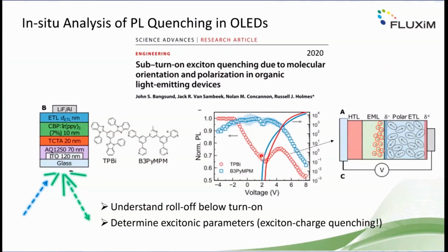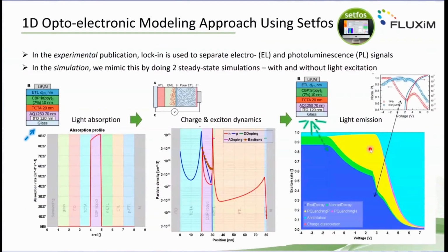For that measurement, of course, you need to excite the photoluminescence by optical excitation, but at the same time there's a voltage scan happening, as this graph shows, from reverse to positive bias. A voltage is scanned, and those carriers that are flowing or which are accumulated at interfaces do influence the photoluminescence efficiency.